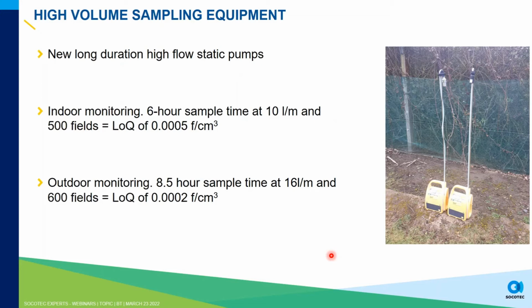And we are currently working on a very large project where there's historical asbestos contamination on site, and there is the risk of the spread of that asbestos around this very large site. And we've been on site now for many months undertaking outdoor air monitoring, but also undertaking indoor air monitoring for longer durations.